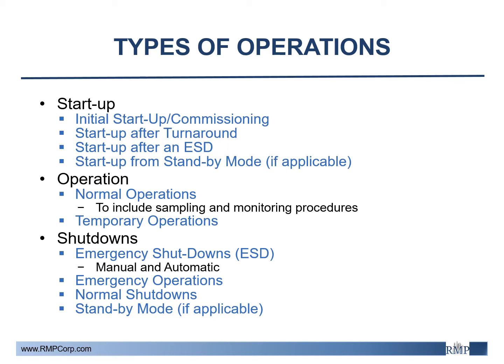The next type of operation to be looked at is standby mode. This is more commonly utilized as systems are becoming more automated, such as there is the ability to temporarily stop operations in a safe manner to make process changes. A procedure for putting the system into standby mode should be developed in a manner that allows a restart in the near future. The system should also be examined to determine whether or not there is a need for instrumentation readings or valve positions to be verified prior to pressing restart via an HMI or other type of control panel.